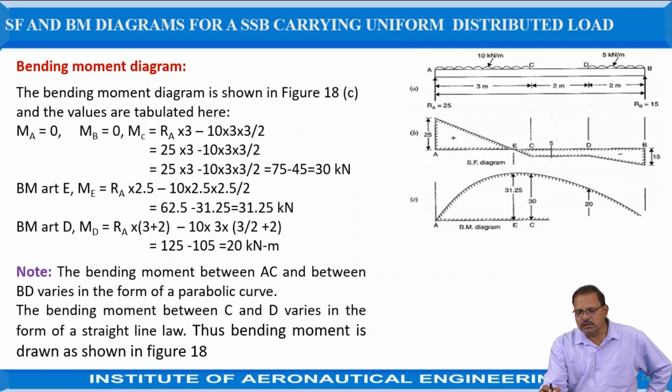In the bending moment diagram, again we require the point E, where it crosses the axis of the beam. Now these two are similar triangles. Here I am taking A1, one more point E, and C, C1. The triangles A, A1, E and C, C1, E are both similar triangles. Here the distance between these 2 points is equal to 3. Hence I am taking x as the distance, and the other is equal to 3 minus x. By using the similar triangles method, determine the value of x.